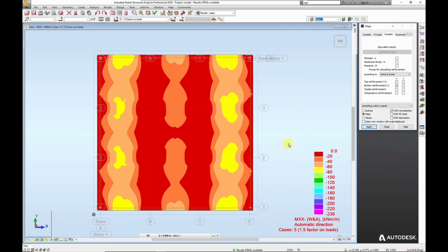We've got these bending moments. We might know that our resistance is 40 kilonewton meters per meter. So again, I can come to here, change that to minus 40. That's my base resistance. I'll choose a smaller value because I don't really think the high value is representative.